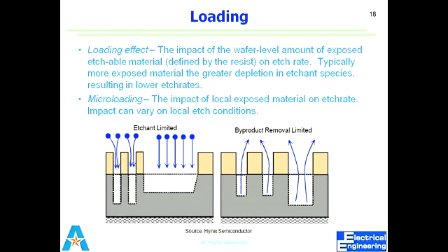It may be due to the number of etchants decreasing in that area, that we call etchant limited, as you see in the left figure, or it may be due to the byproducts that are formed not being efficiently removed from there. So if you remember, even in dry etching, even in wet etching in the lab, we move it a little bit. That movement is actually making it uniform etching, because I want that on the exposed part where